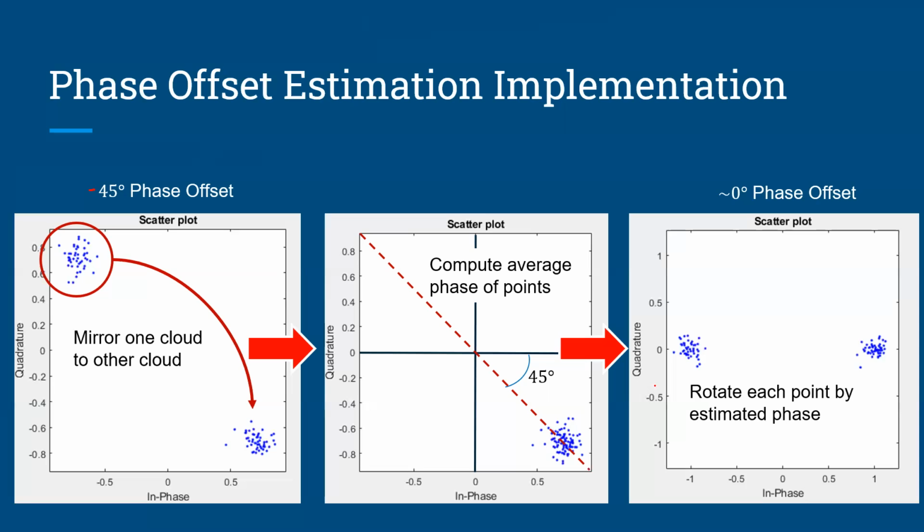And so then you can do what's called channel equalization, which is kind of canceling out the effects of the channel, like the attenuation and the frequency selectivity of the channel, which might be the case. So some frequencies might be attenuated more than others. And so that'll allow you to estimate those effects and cancel them out. So that's another application of packet headers.